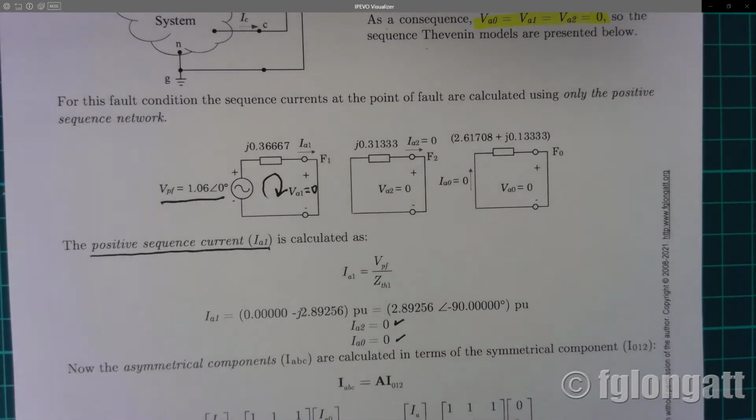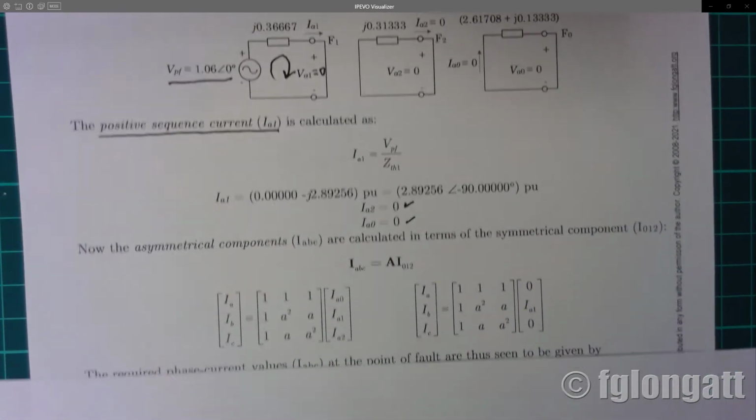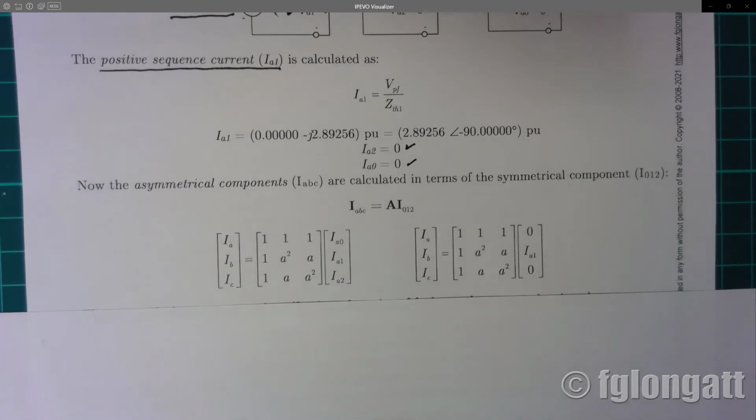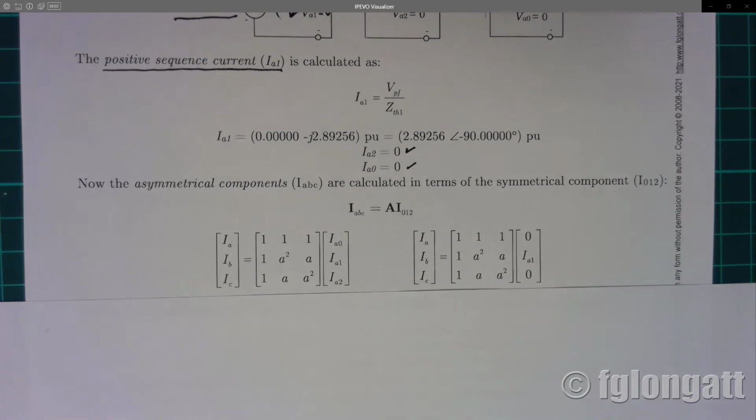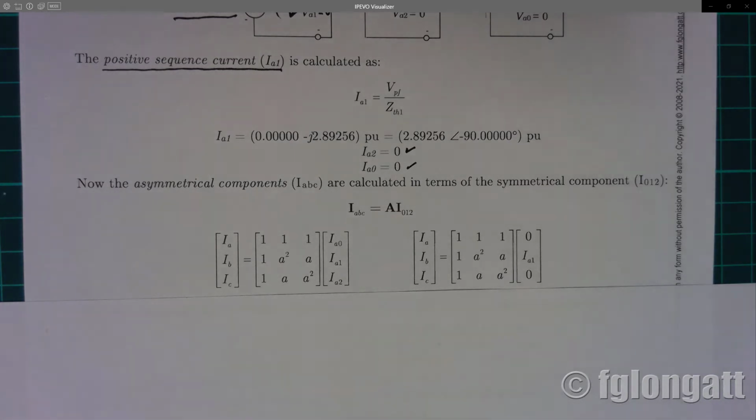Well, what I will do now is my main objective today. What is my main objective? We are talking about symmetrical components, and I would like to show you that even if we are working inside a symmetrical fault, and this is the case of the three-phase short circuit, remember, a symmetrical three-phase short circuit is a symmetrical fault, we can use symmetrical components to calculate the currents, okay?